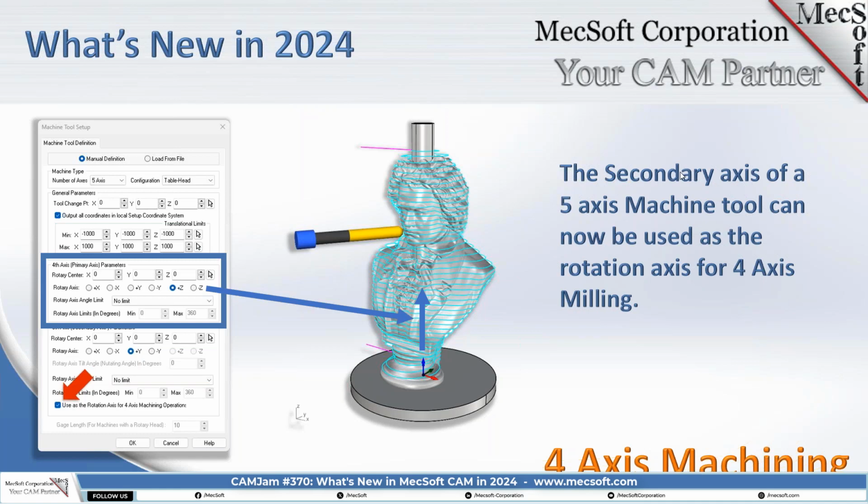Now you can set your machine to 5-axis mode, and you can run 4-axis operations in the 5-axis mode using the Z-axis as your primary 4th axis. Set that to Z. Normally this wasn't available, and up until now, these were grayed out. So now you can use the Z-axis, both positive and negative Z, for doing 4-axis cutting in 5-axis mode.